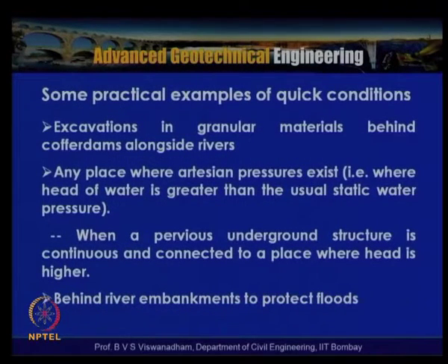Some practical examples we also discussed. They are excavations in granular materials behind the coffer dams alongside rivers; any place where artesian pressures exist, that is where the head of water is greater than the hydrostatic water pressure; or when a pervious underground structure is continuous and connected to a place where the head is higher; or behind the river embankments, that is levees, which are constructed to protect against floods.